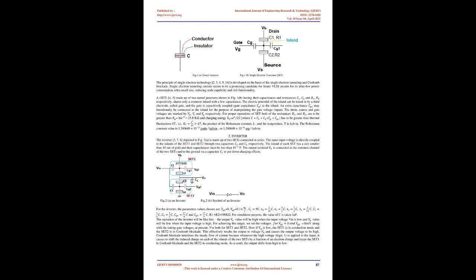1. Coulomb blockade and single electron transistor. A tunnel junction in Fig. 1a comprises a thin insulating barrier between two conducting electrodes. It has a capacitance C and a resistance. The electrodes of the tunnel junction may be superconducting or semiconducting. Electrons with one elementary charge, 1.602 times 10^-19 C, carry the current.